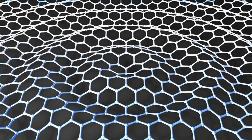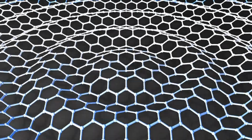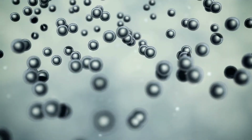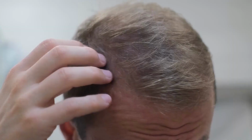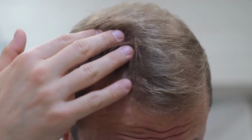The raw polymer is melted and forced through extremely small nozzles in a process known as spinning. As the material passes through these tiny openings, it forms very thin filaments. Each individual filament typically has a diameter of only 5 to 10 micrometers. To understand how small that is, a human hair is roughly 10 times thicker.